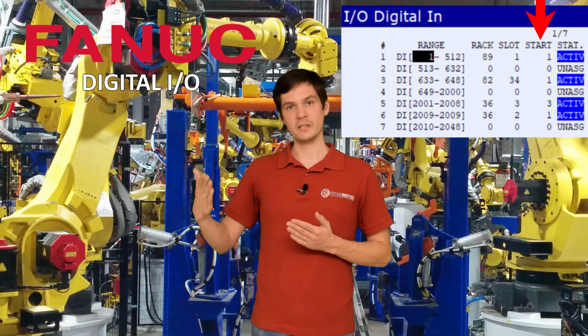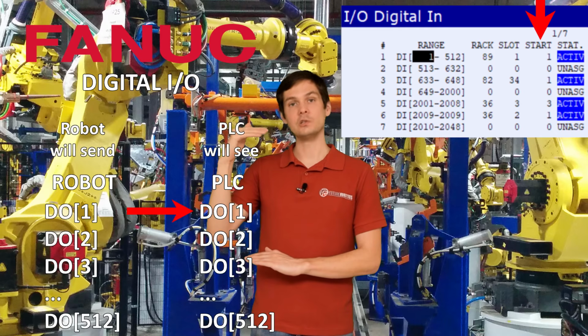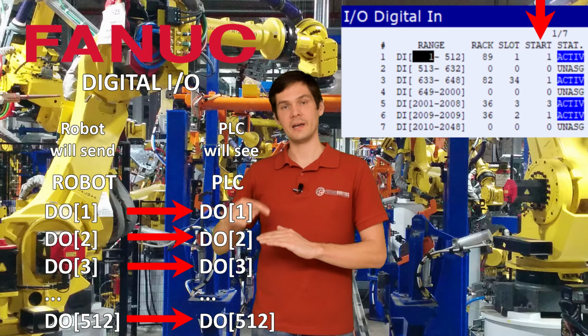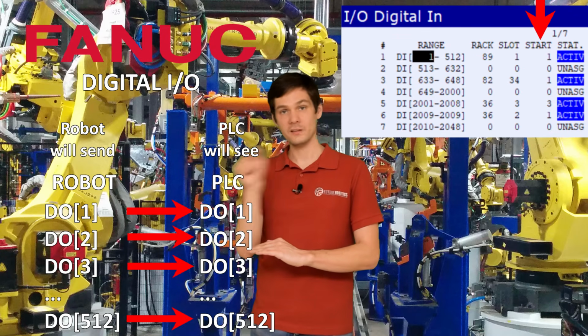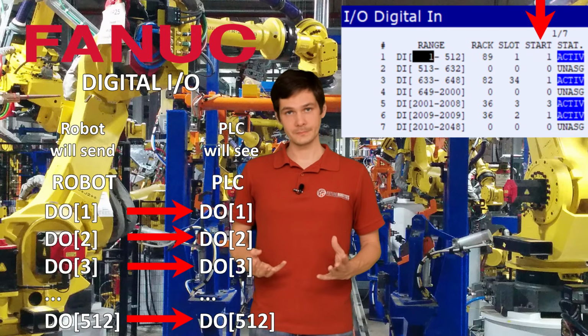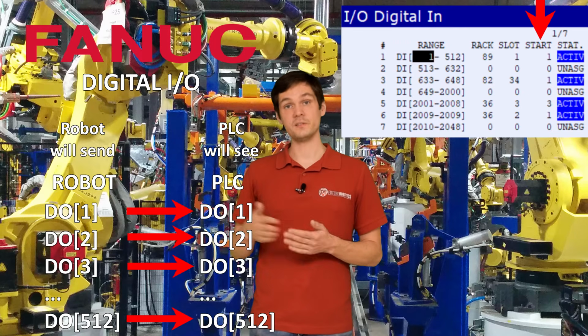So over there, if you put 1, that means if you have the 512 bits, you will start counting from number 1 to 512. And then bit 1 is going to be output 1, bit 2, output 2, and so on and so on. If you change the start number to a different value, that means you will just start counting from that value because it's your start point, right?